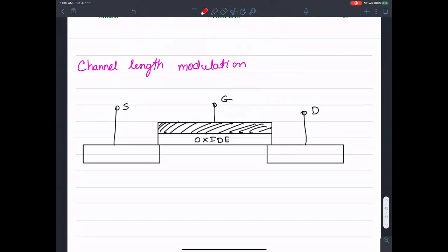The way the MOSFET operates, as you know, is when you apply a positive voltage, electrons are going to line up underneath the gate. When there is enough positive voltage on the gate, meaning that VG is greater than V threshold, there's going to be correspondingly enough electrons to form a continuous channel between the source and drain, correct?